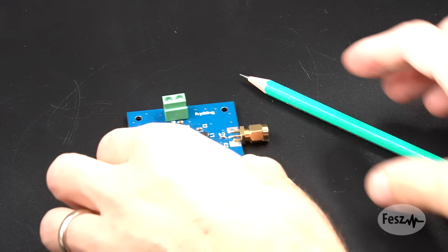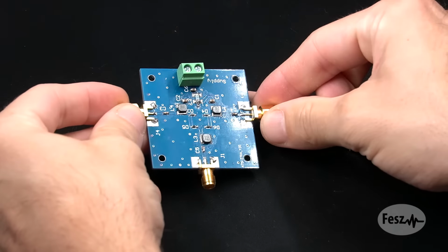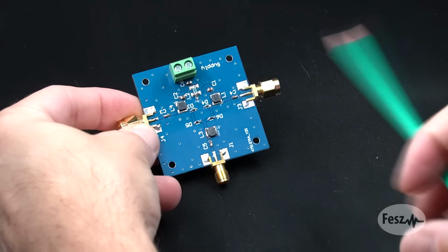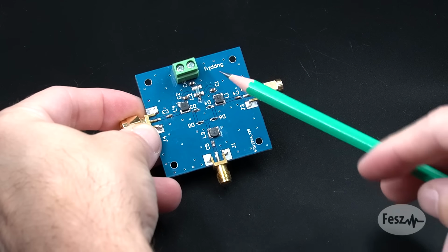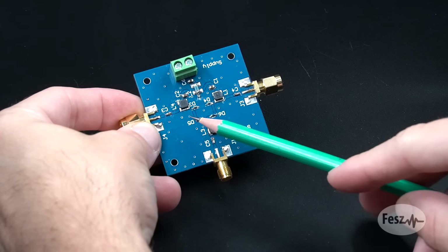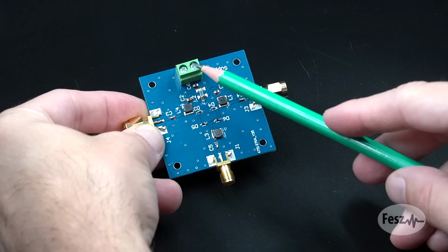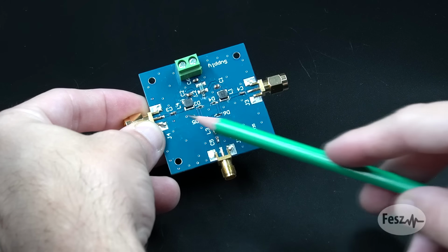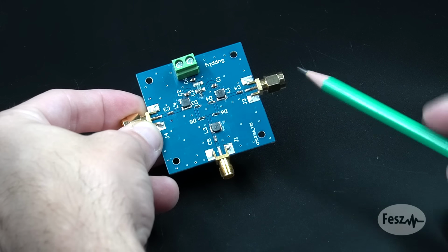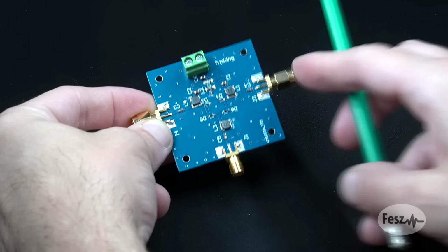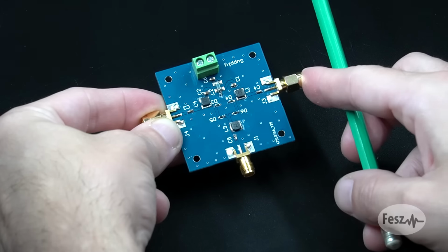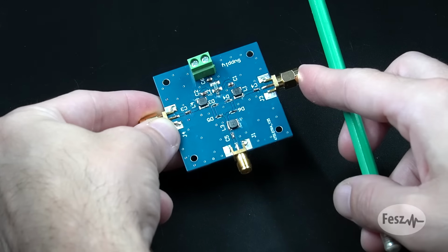The design was built on a single layer, with the second layer of the board being kept as a ground plane reference. All of the components nicely flow without any bias or other tricks. The control signal is applied on the top side, the input signal on the bottom, and then the two outputs are to either side. So the signal coming in from the bottom should be going out one way or the other, depending on the polarity of the control signal.